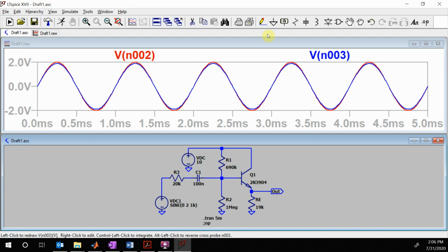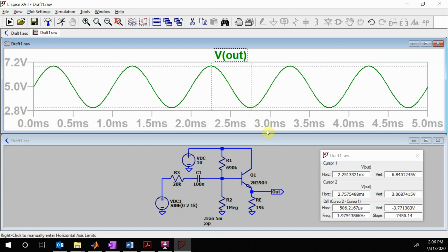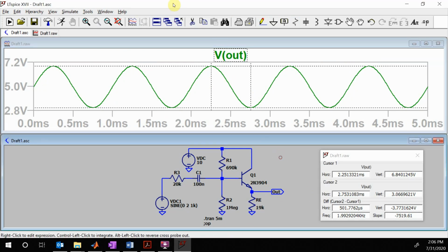And then we wanted to make sure that our output impedance is okay. So right here, you see this is now about 3.77. And we're going to add in a resistor here.